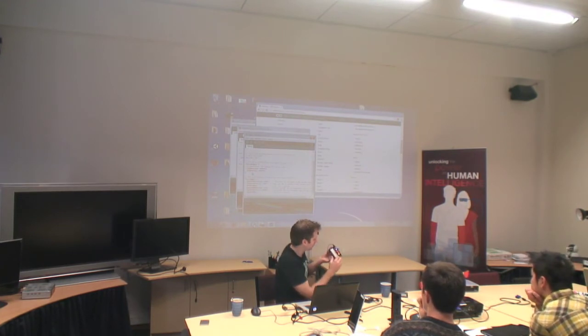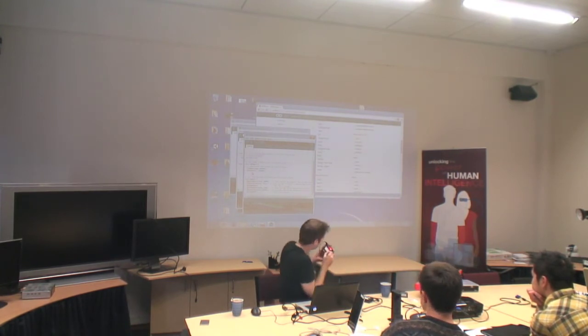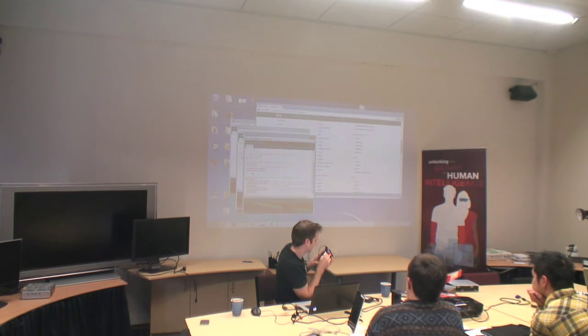For the parts in the middle, they connect in the opposite direction. In the rails, these all connect vertically like that, but there's no connection horizontally, so this one doesn't connect to this one. Whereas on the breadboarding surface, it goes the other way. All of these are connected in a straight line, but they're only connected to the ones to the side of them. You see we've got this sort of ridge running down the middle that actually splits them.